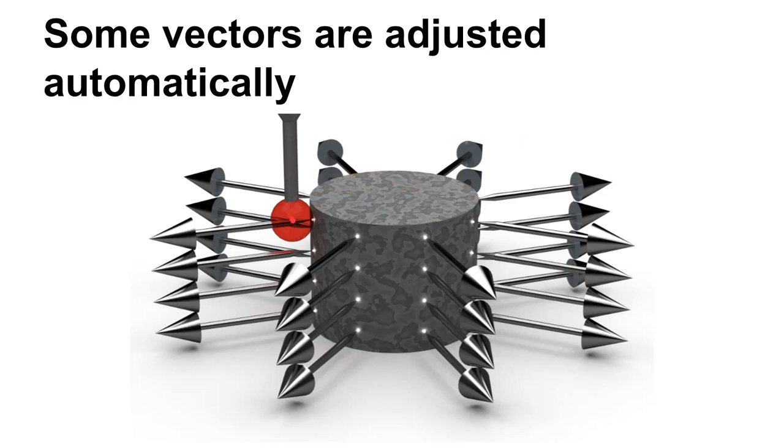For instance, if we're probing a cylinder and we take all of these points on the cylinder and we tell the CMM, hey, look for a cylinder out of these points, then what it can do is, even if you didn't probe these exactly traveling in, and you actually can't manually do that, you cannot manually drive perfectly normal to this surface like this, but if you took enough points around here and said, hey, do you see a cylinder, then it would do some best fit analysis and it would fit a perfect cylinder to those points.